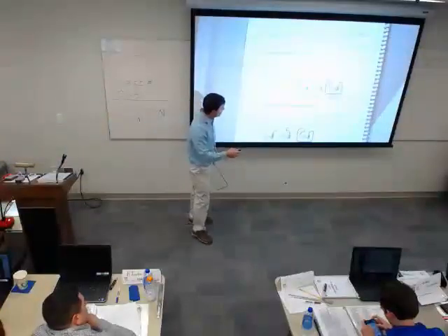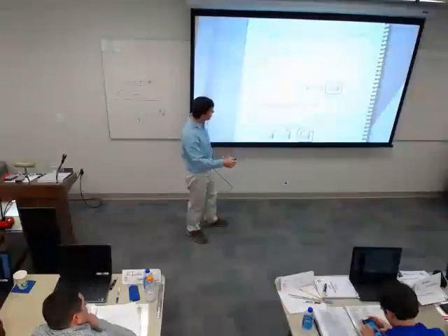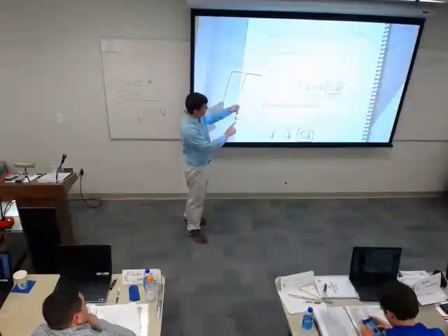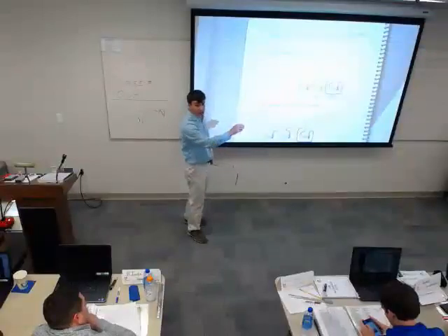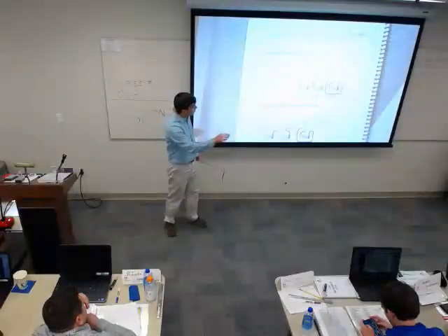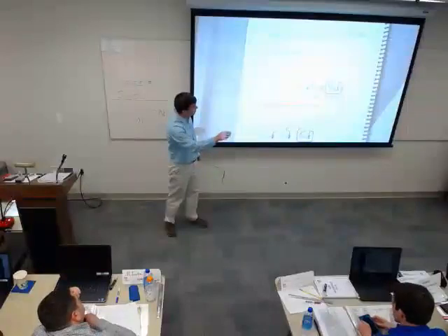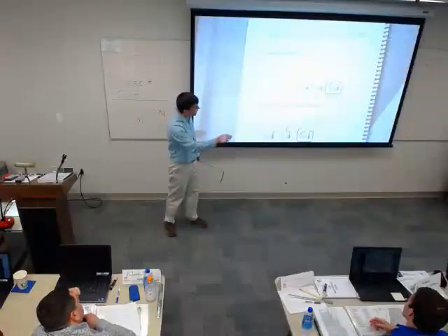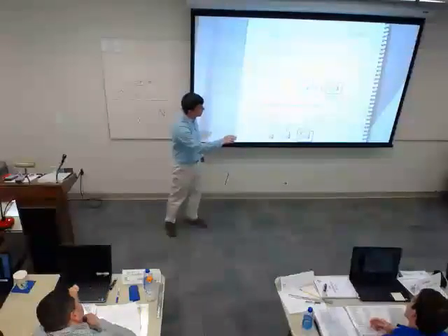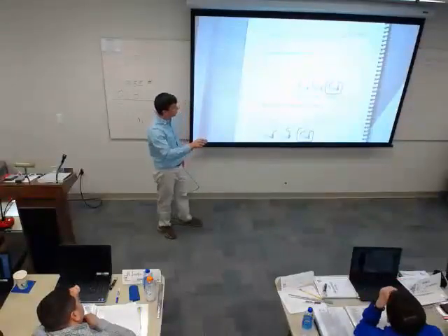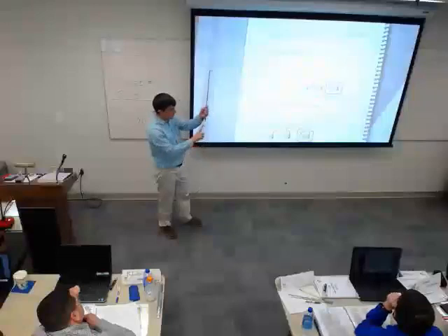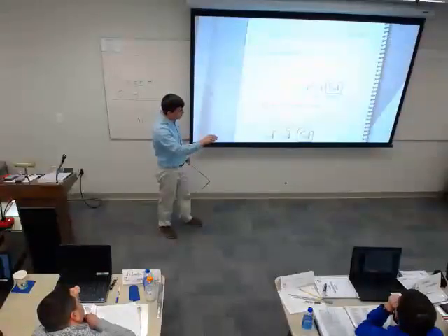So if I want to know just static pressure, that is this port. So I would measure, and this is assuming I have positive pressure. If I want to know just static pressure, that's the one going around the holes inside, I would hook this up to this side, and you can see that it would push that water column down, and I can read just my static pressure. If I want to know just my total pressure, I can hook up to this port, and it's going to move that water column down.